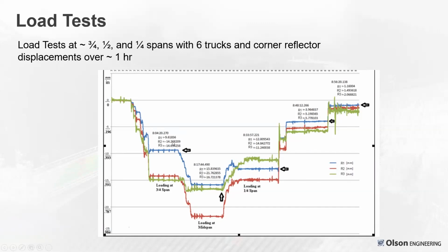So these are the deflections that are shown. You can see that the loading at mid span, when the trucks were right over it, definitely resulted in the most deflection, about 0.85 inches. You'll see that precisely in a minute. At mid span, out of receiver 2.